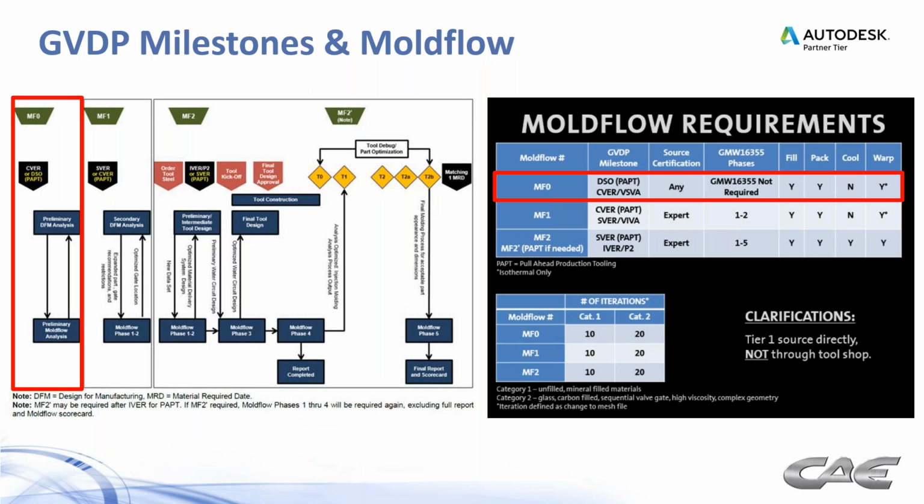Because it always had to go up the chain to get 100 signatures to make a design change, and meanwhile the mold maker is waiting to start cutting steel. So that's not the best use of Moldflow analysis. Really, the best use is well ahead in the design stage, so that you can affect part design to the extent that it improves the things you want to improve.